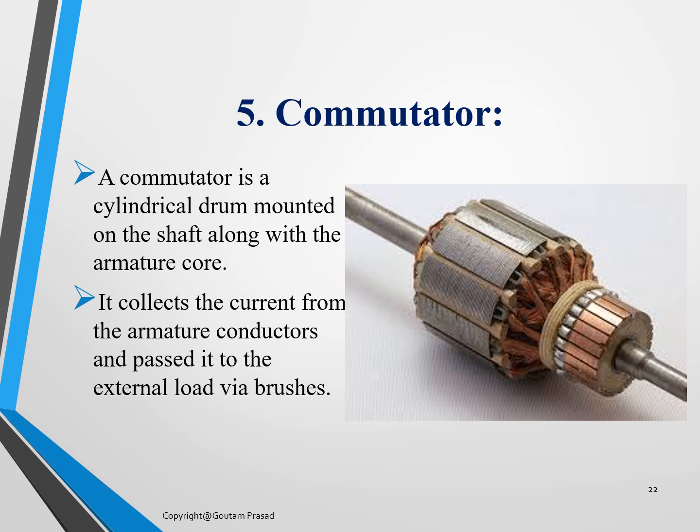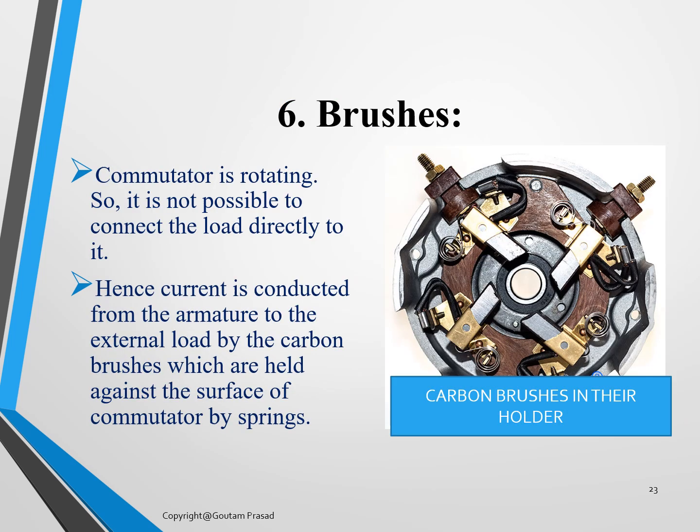But in the case of a DC motor, these commutator bars collect current from the DC source and feed it to the armature coils so that it creates its own magnetic field and interacts with the permanent electromagnets' magnetic field created due to the poles.